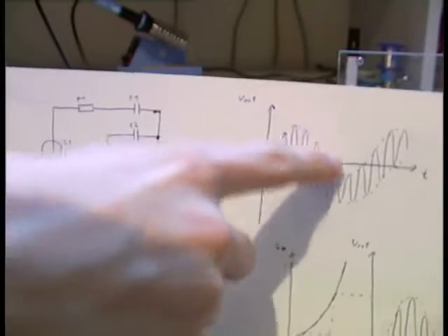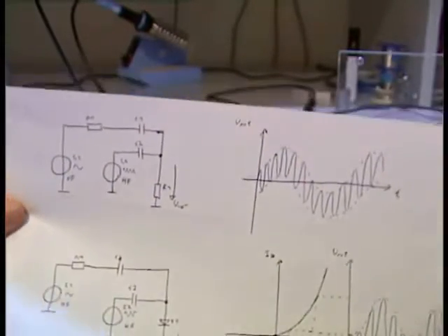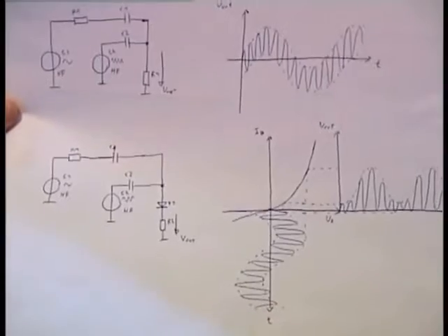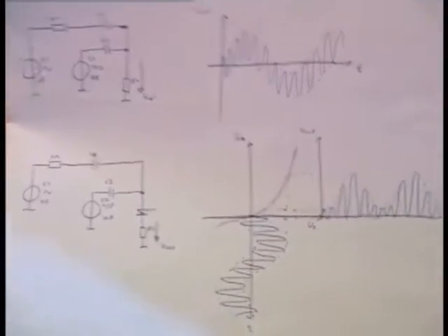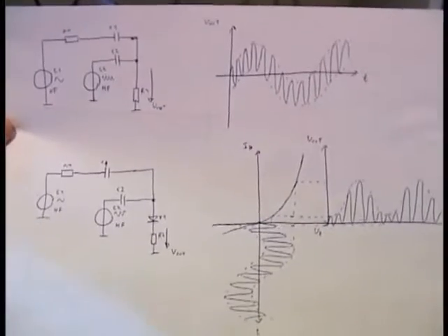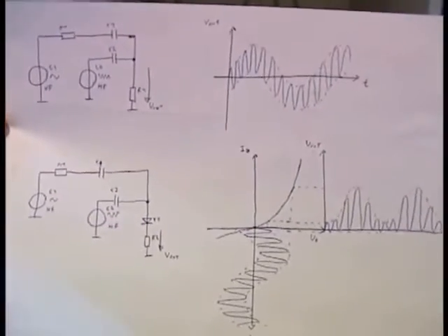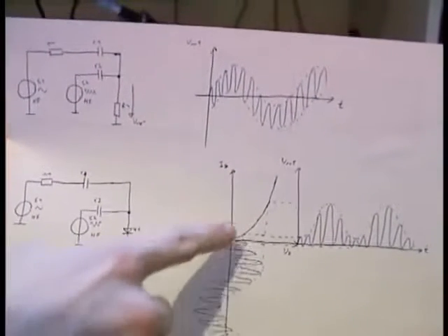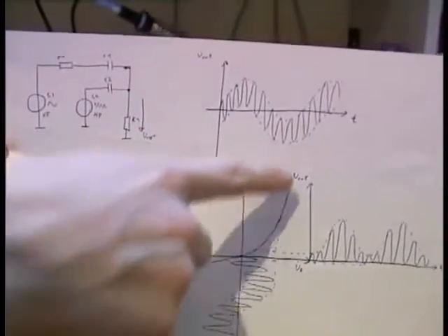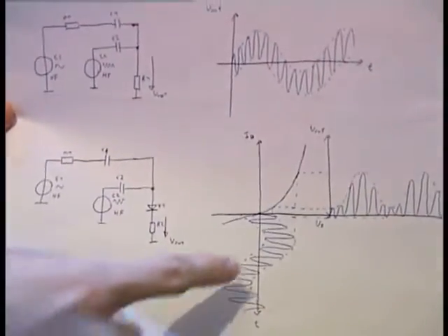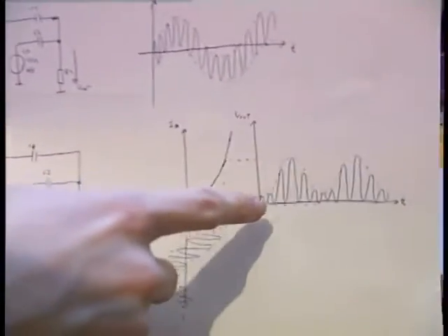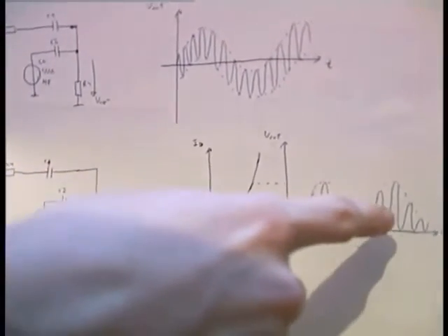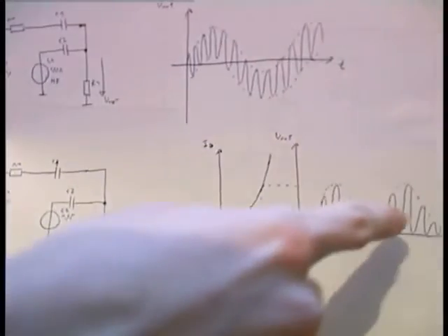You can see it's going this way, but we want an AM modulated signal, and for this we need a non-linear component with a non-linear characteristic, like a diode you can see here. Now we are also adding both signals together here, but on the characteristic of the diode you can see the added signal goes this way, and then we have an amplitude modulated signal, not fully amplitude modulated but half amplitude modulated.